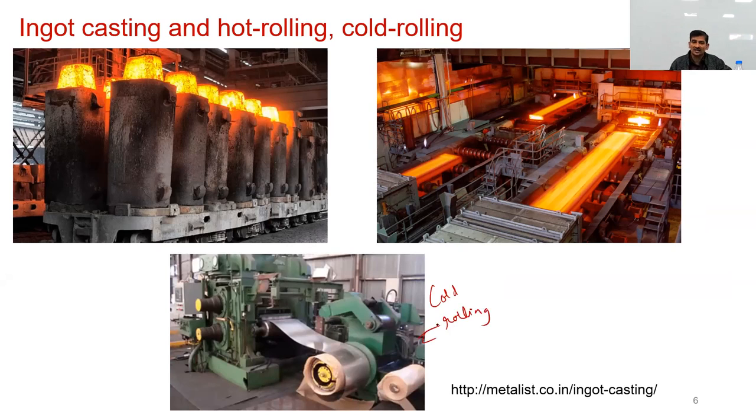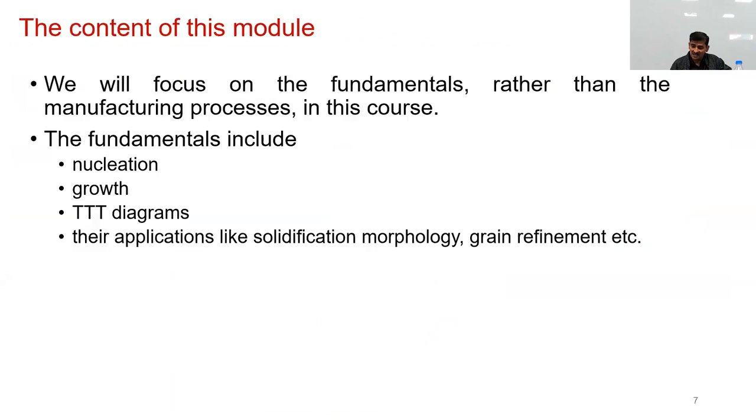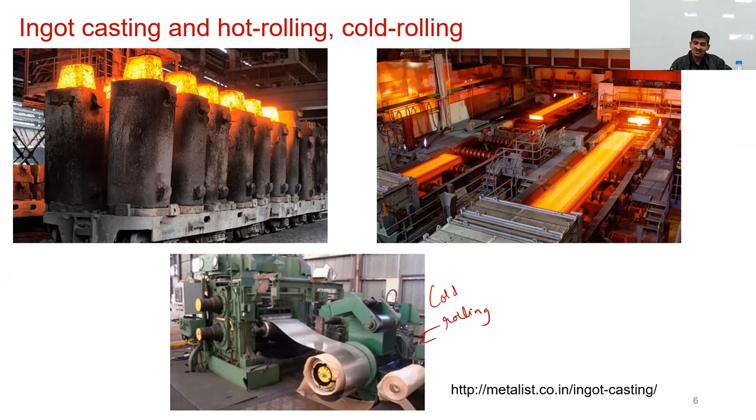So this hot rolled metal undergoes cold rolling inside a set of rollers, as shown in this figure. It's a proper industrial workshop. As you can imagine, the starting point for all of these materials is essentially cast ingots, as shown here. Although casting solidification may not be directly relevant, it does play a role in affecting the final structure and properties of the cold roll sheet.